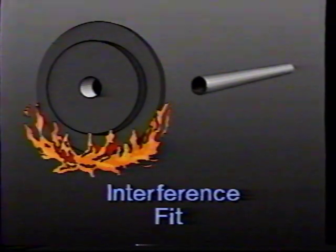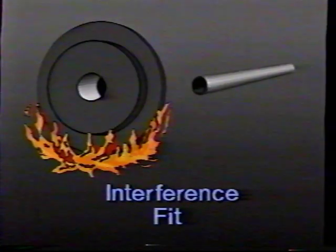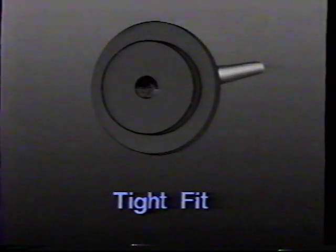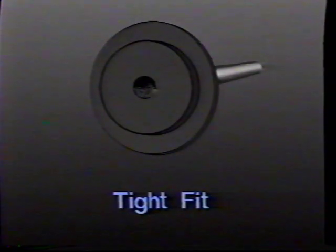The wheel is heated, causing the metal to expand and increase the size of the hole. The axle is chilled, causing it to shrink to a size that produces a clearance fit, permitting the axle to be assembled with the wheel. Once the assembly returns to a normal temperature, the wheel and axle go back to their machined dimensions, producing an extremely tight fit. Let's briefly review the terms and concepts covered so far.